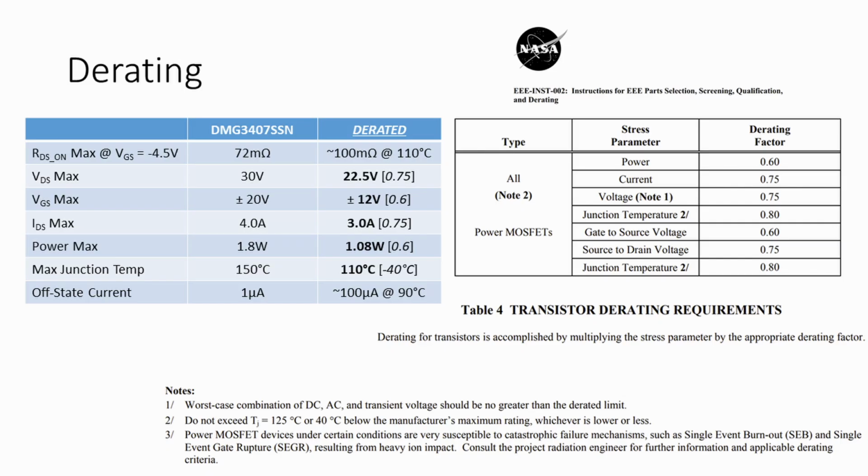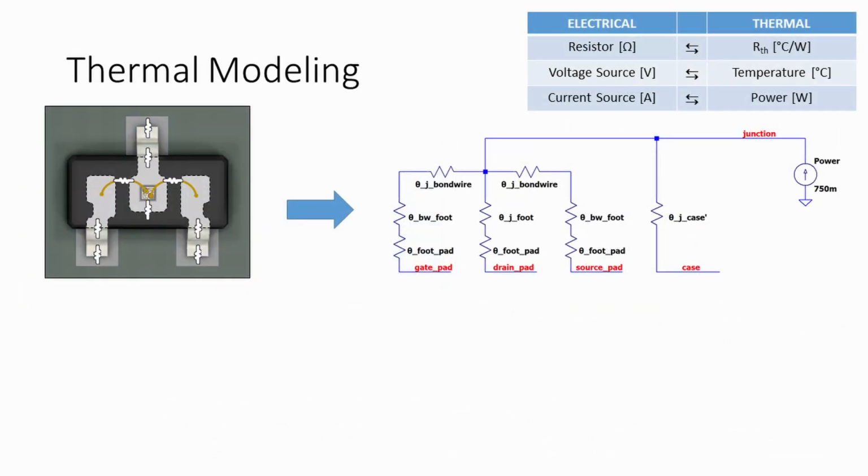One other item to highlight, probably the most important part of derating and the biggest impact on long-term reliability, is junction temperature. This is the temperature of the hottest part of the silicon die and drives power dissipation limits. Understanding thermal performance is a key part of electronic design. Luckily, thermal design can be modeled with circuits, which are then solved with regular circuit techniques.